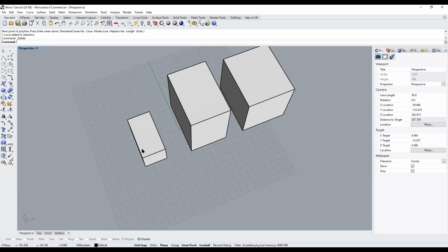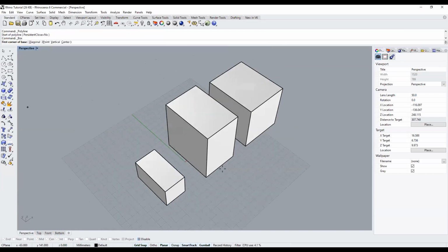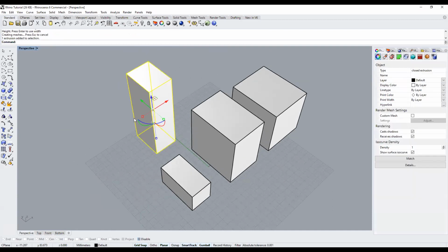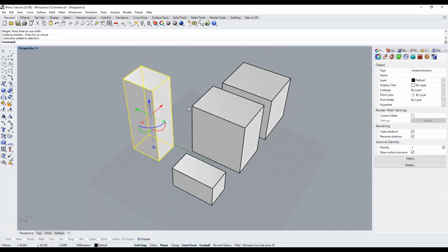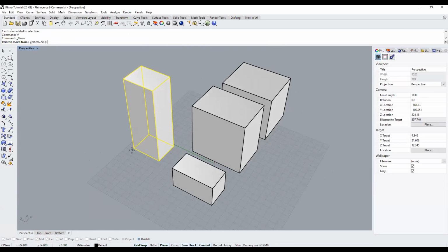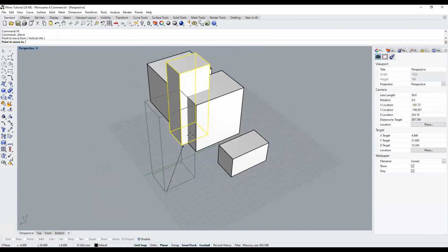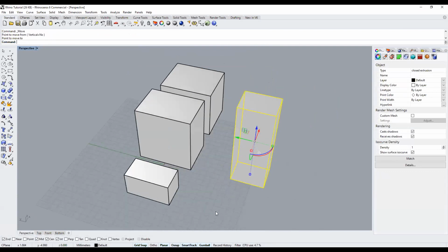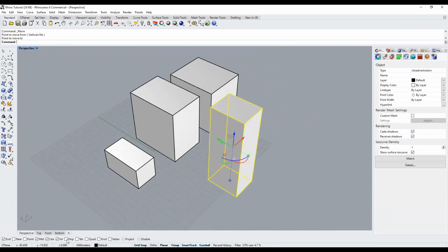And for object snap, normally if you don't turn this on, you can't say you want to apply this object on top of this. You can't really stack it onto anything unless you turn on object snap. So once you turn this on, there are a few options that come up. So this is the end, near, point, mid, center, intercept.